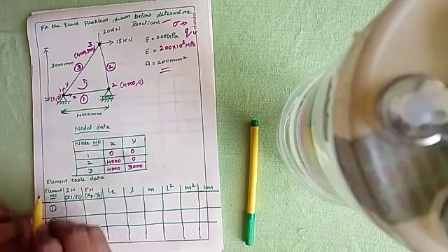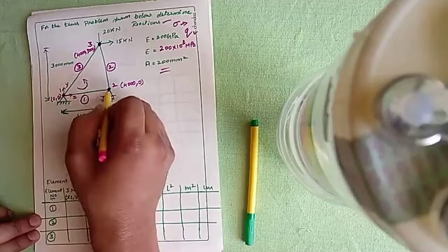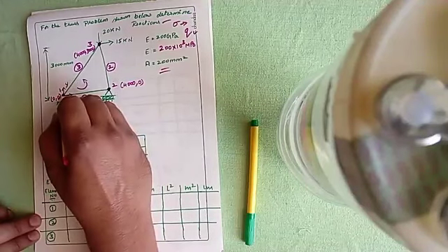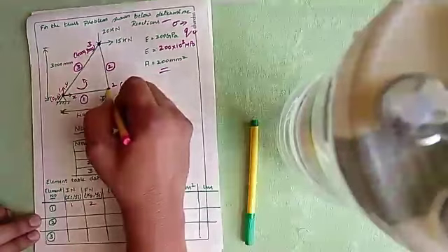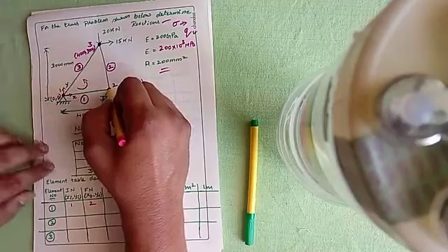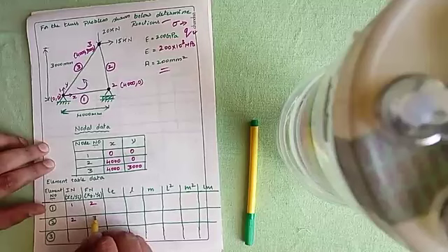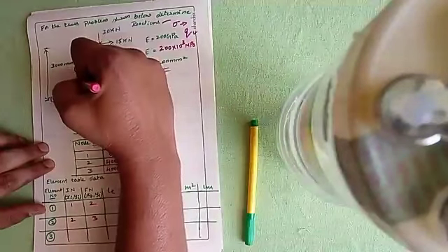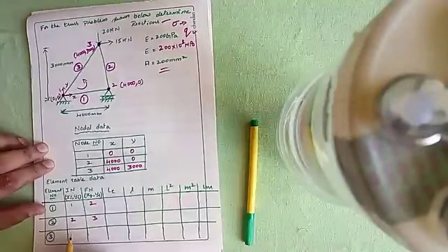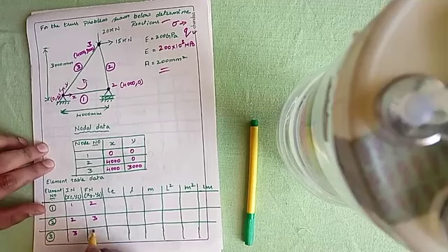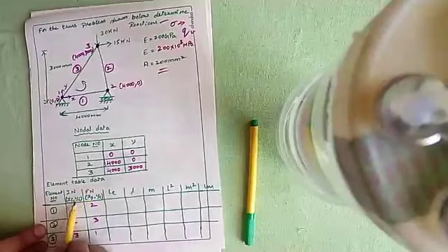Now the element numbers, which I've given in a counterclockwise direction. You have to club 1 and 2. Since you're going in anticlockwise direction, the initial node for element 1 is 1, and it ends at node number 2. Now you are at this location. For element 2, the initial node is 2 and the final node is 3. Now you are moving in anticlockwise direction, so for element 3, this is the initial node and this is the final node: 3 and 1. Here, in is the initial node, and fn is the final node for that element.